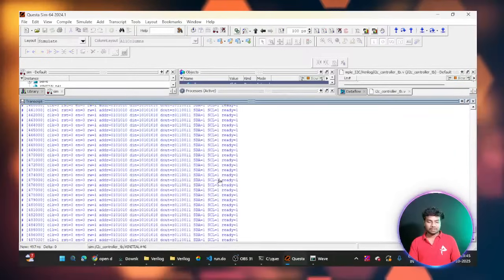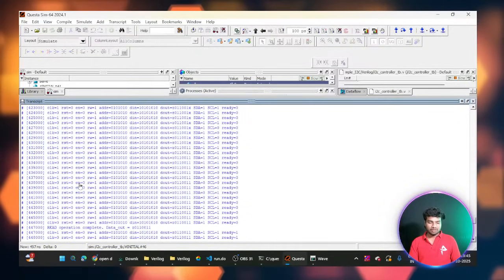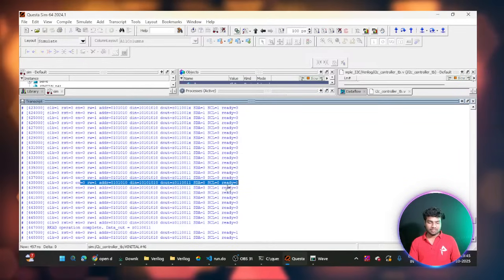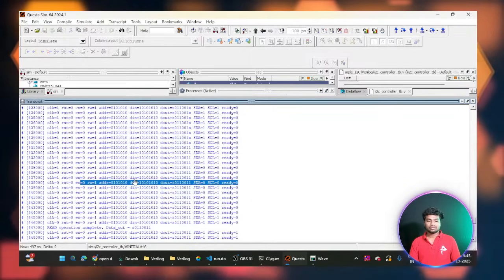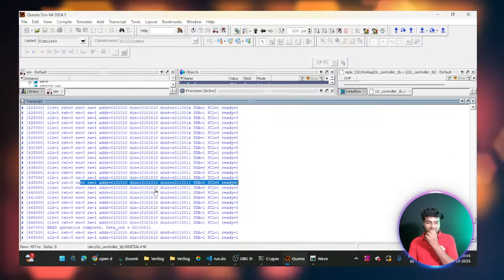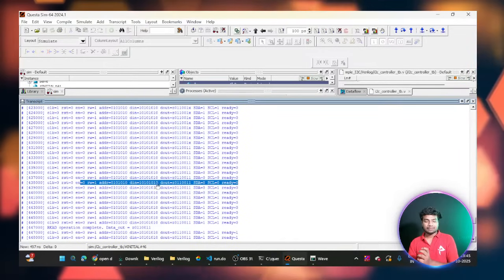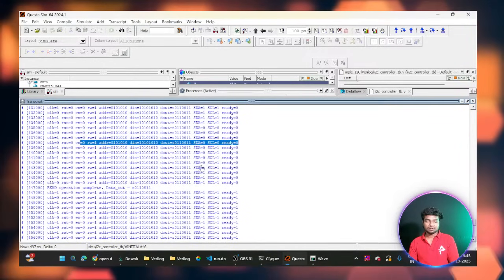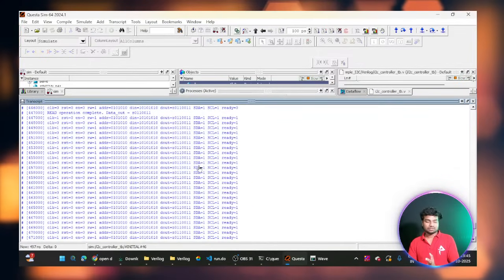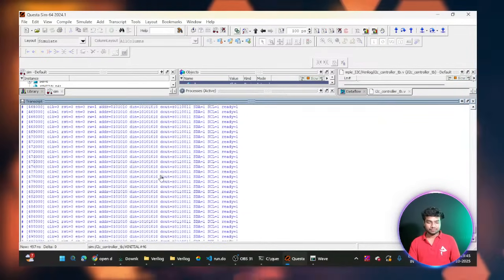Read operation completed. So you can see here read operation. You can see the output like Z01110011. So this is my output signal. What I have written into my address with D in, I am reading from that place. This is my output signal. So ready is 0. So this is how it works. So this is how we can verify the I2C simulation.